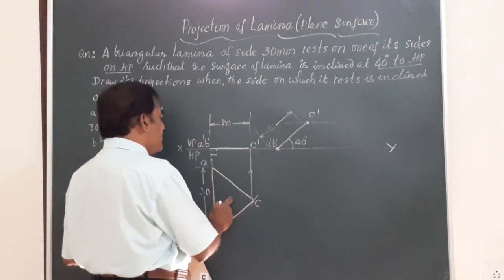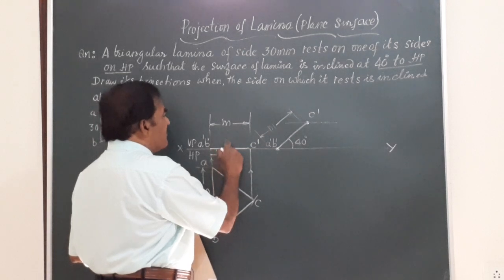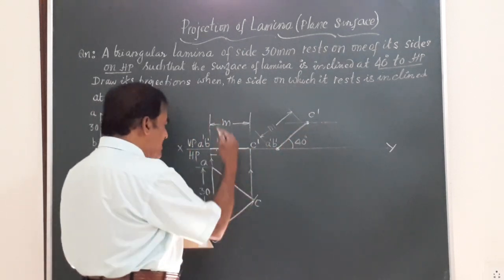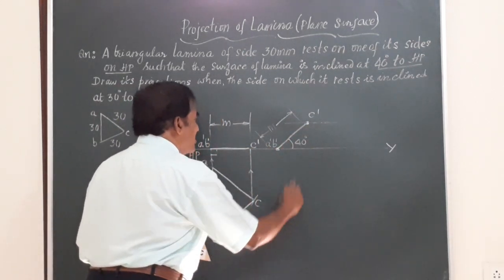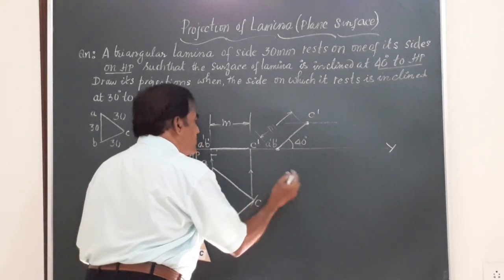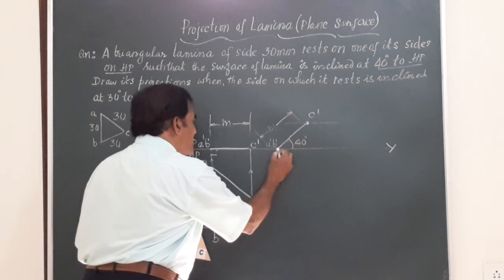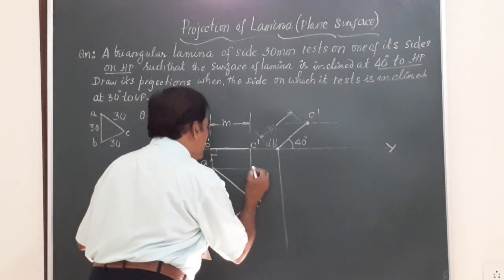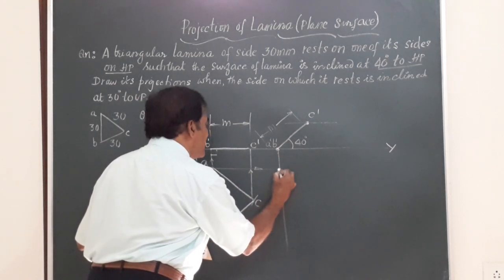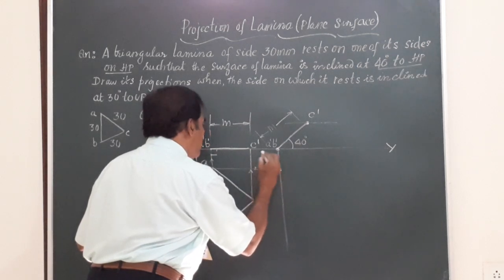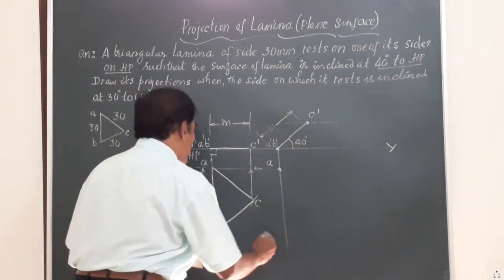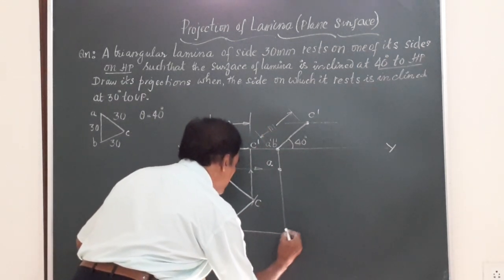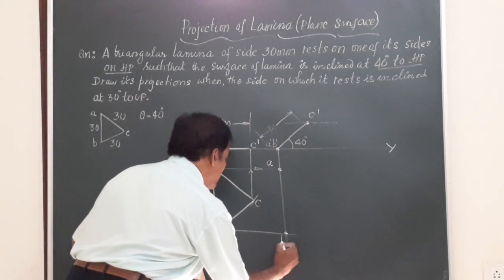Now we had the top view, we got the front view. The front view is written here. We should know what we are going to get here for the corresponding top view. So the procedure is, draw a vertical line from there, a horizontal line from here. The point where those two intersect is the point A. Likewise, a vertical line from B, a horizontal line from B. Friends, you get the point B.